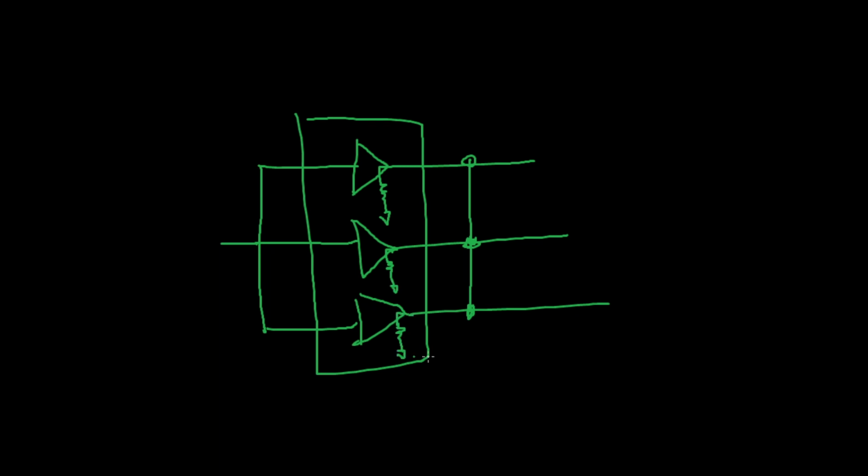It's actually incredibly uncommon to need to do this. The only time I've seen it really required is if you're trying to push a device all the way to the very bottom limits of its voltage range, or maybe even a little beyond the bottom limits. So what I was showing earlier with the RDS on plot, if you're looking at how resistance increases as you decrease the voltage supply.